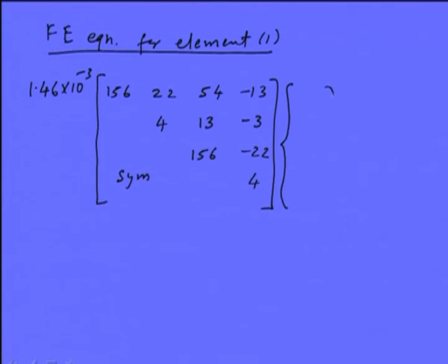Here we have the acceleration vector, given as W1 double dot, with a time derivative, then W1 prime double dot. Prime represents the derivative with respect to the spatial variable x, and this is for W2, and this is W2 prime double dot. Prime represents the slope. So this is the mass matrix.